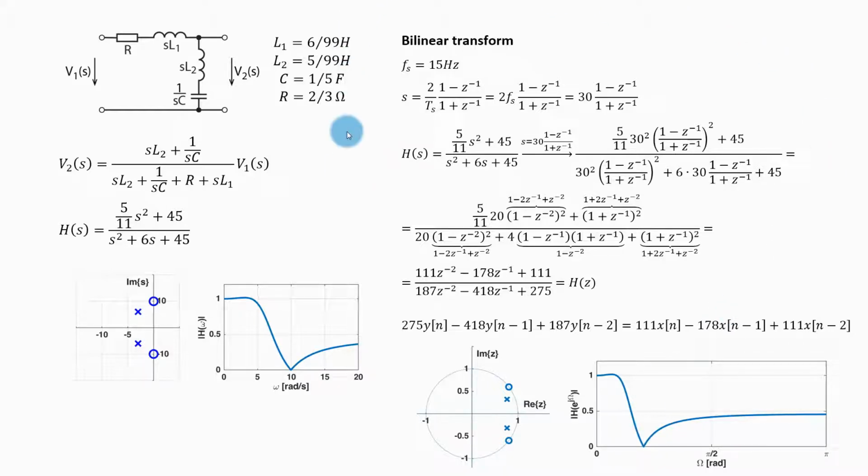So this is the discretization using the bilinear transform. Again, all you need to do is just this substitution, except this time you can look forward to the shape of your frequency characteristic being preserved.